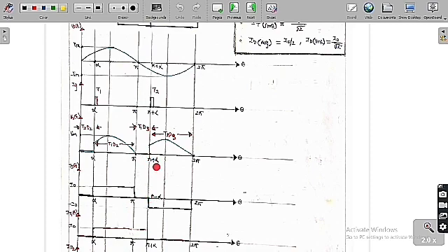Whereas at pi plus alpha we are going to trigger T2. So T2 is going to turn on, and as T2 turns on, D3 is also going to be on by default. Therefore T2 and D3 conduct. If you apply KVL, we get V naught of t equal to minus Vs of t, so it is the negative of Vs of t. So we are going to get this graph. From pi plus alpha to 2 pi, T2 and D3 conduct.